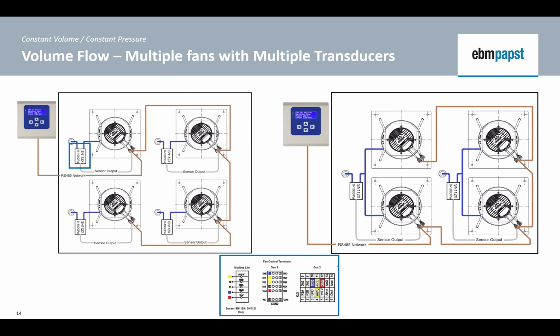Each fan can have its own individual pressure transducer to provide feedback to the MDC controller, or the sensors can group together several fans in the array using an average pressure measurement circuit.